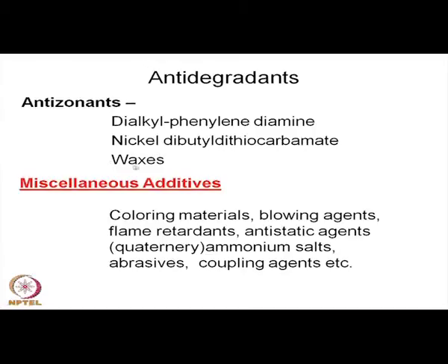That wax is saturated, so that thin saturated layer prevents ozone from entering the vulcanized rubber surface. So, that prevents degradation by the action of ozone.